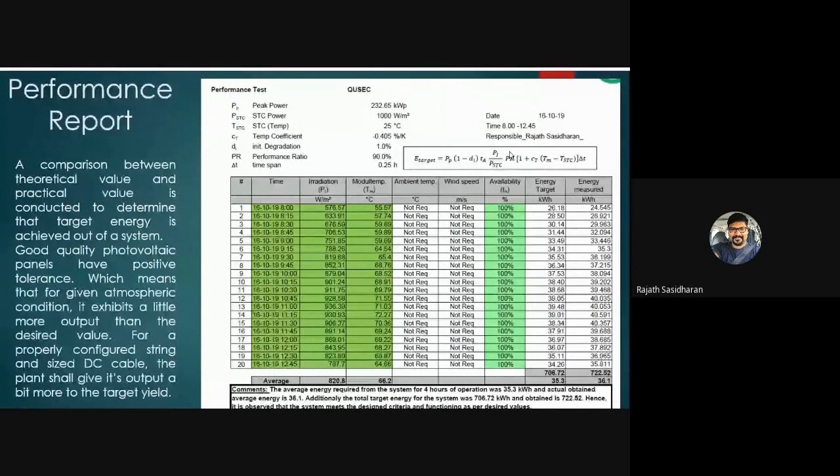So that's why there is a linear performance warranty term associated with such solar photovoltaic panels. A good panel manufacturer will give you ideally 25 years of service life, but they have a clause along with it that every year the degradation is 1% or more. The initial degradation we consider because the panels may be 1 year old by the time they are shipped, exported to site, and tested and commissioned. It can take up to a year depending on the size of the photovoltaic plant.